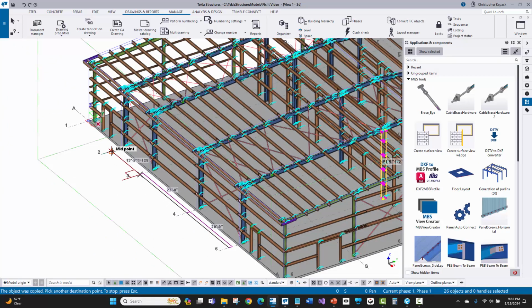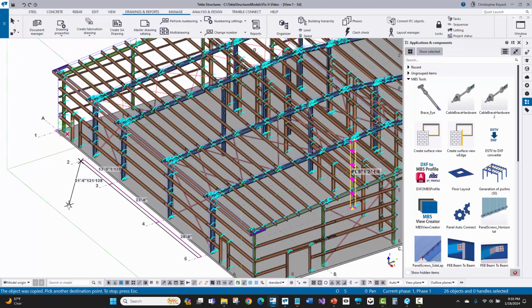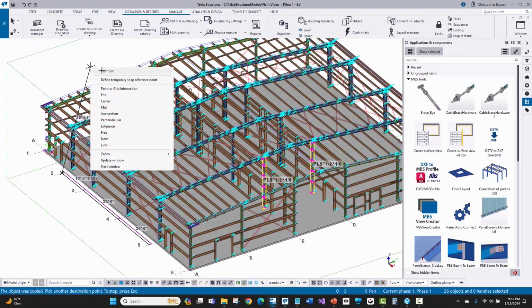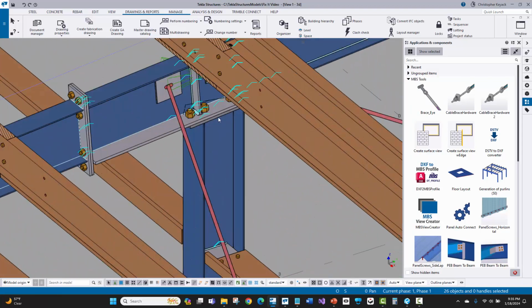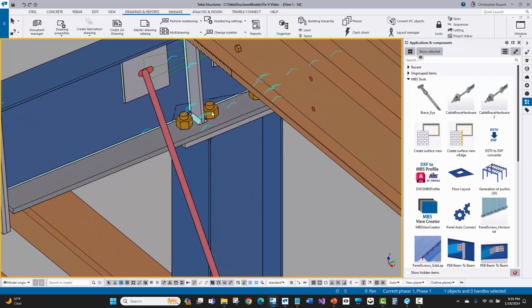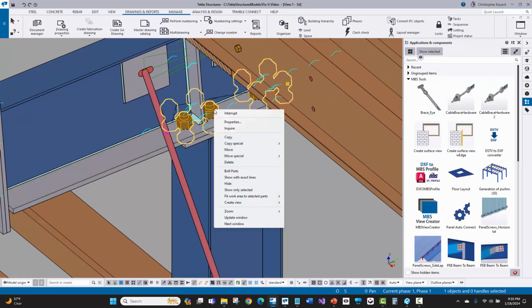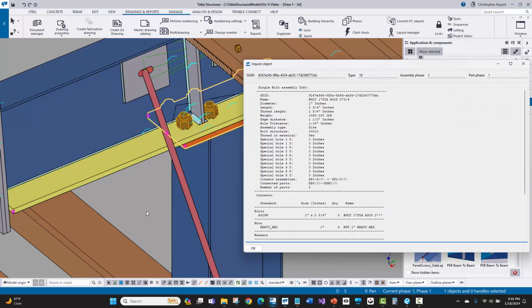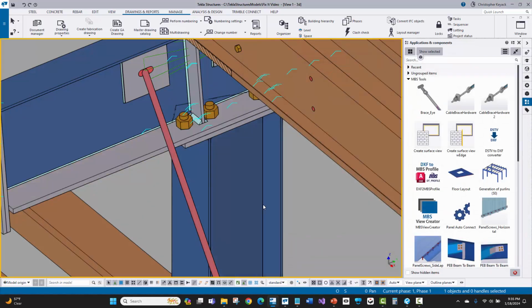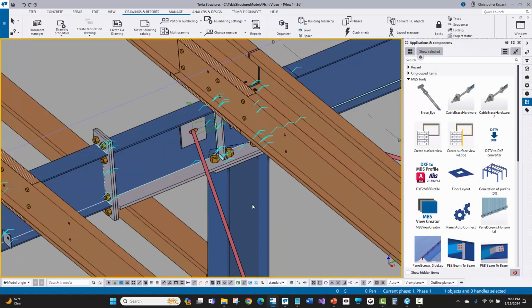And again, here I can very quickly see without having to zoom in that I can trust that I'm going along this line and that the copies are going in exactly the right location. We'll interrupt and then let's zoom in and see if that's correct. Now, when I see that here, we'll see that these bolts copied across and they did mate with the existing rafters that were there because the bolts had disappeared when I deleted the columns out. But that copy worked because all the geometry is exactly the same on all these rigid frames.